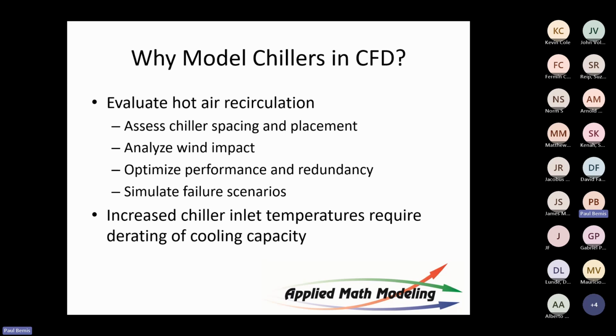And you can do mathematics, algebra. You can say, well, look, I've got 400 kilowatts of total load, and so I should use two 400 kilowatt chillers. That gives me N+1, should be fine. And generally, that's okay. But as we continue to drive up the density of these data centers and try to do more and more, that rooftop gets crowded, or the space beside the building gets crowded. And when it gets crowded, you've got to space things closer together. When you start spacing chillers close together, it can cause issues, as you will see.